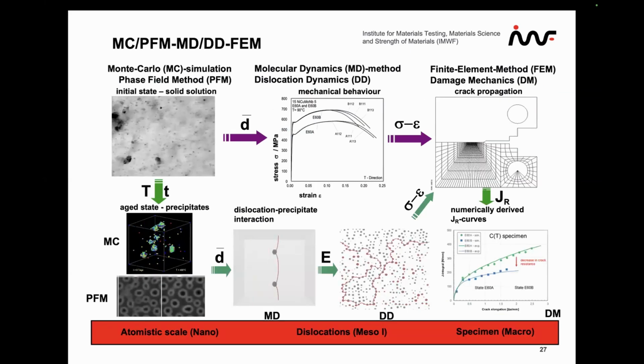Let me now show you the first, to my knowledge, successful multi-scale example. It is based on a number of projects which have been funded from a German research society with respect to atomic power plants and safety analysis, where copper precipitates were forming during the service conditions, 340 degrees centigrade over 10, 20, 30 years lifetime and more.